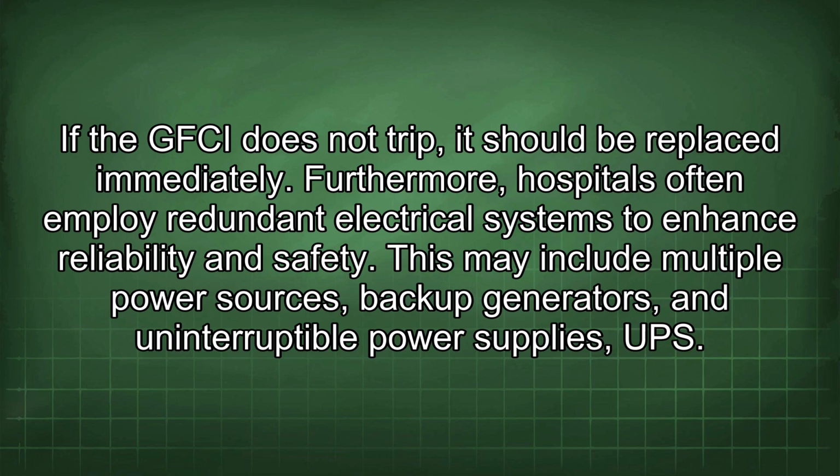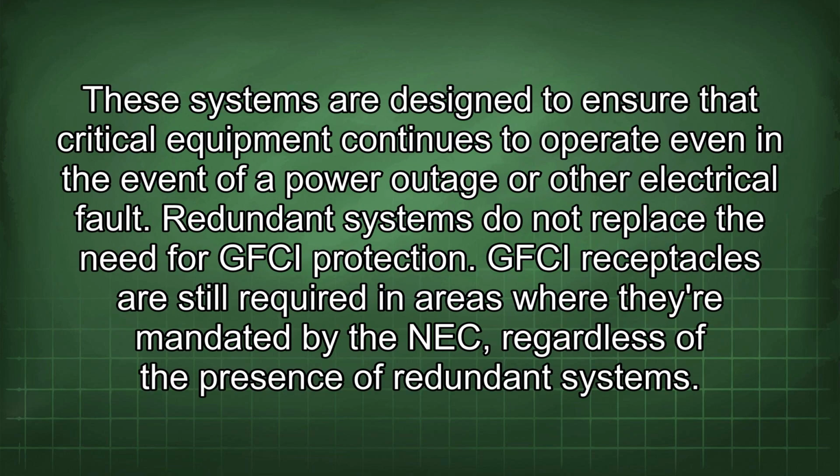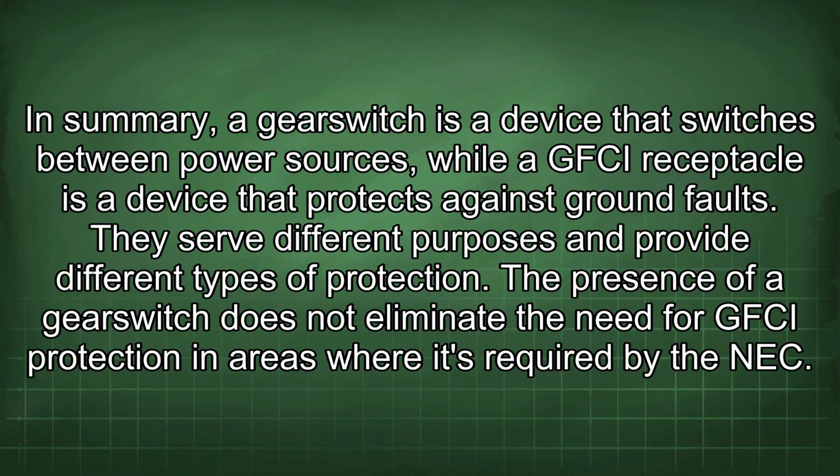Furthermore, hospitals often employ redundant electrical systems to enhance reliability and safety. This may include multiple power sources, backup generators, and uninterruptible power supplies (UPS). These systems are designed to ensure that critical equipment continues to operate even in the event of a power outage or other electrical fault. Redundant systems do not replace the need for GFCI protection. GFCI receptacles are still required in areas where they are mandated by the NEC, regardless of the presence of redundant systems.